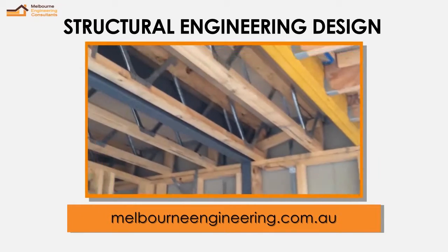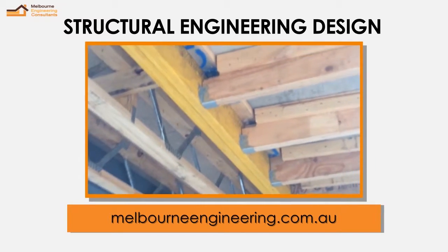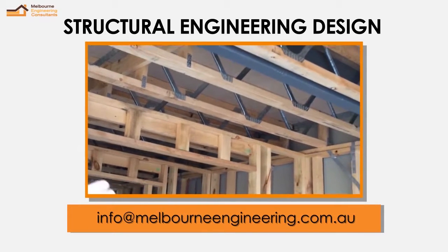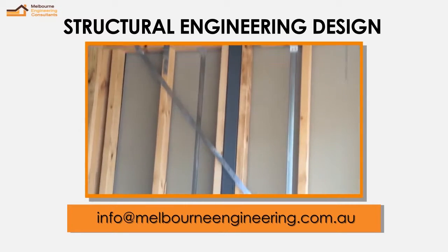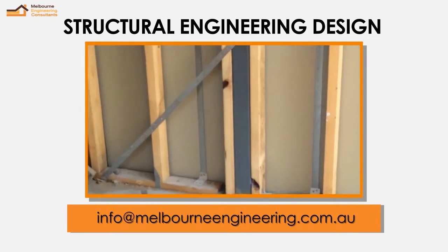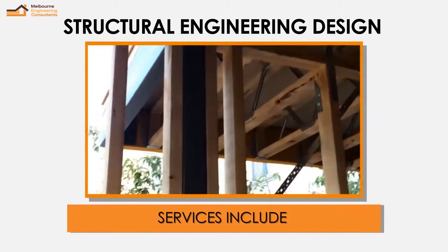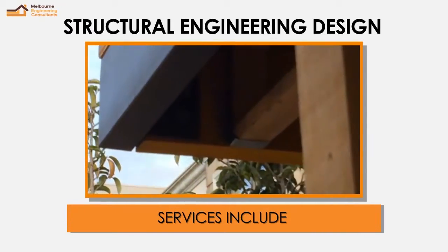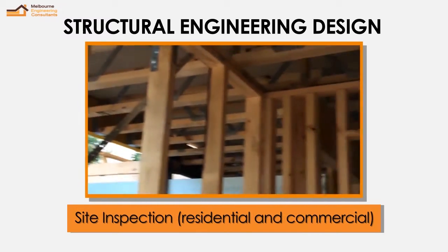So here we're showing the ground floor, so showing the balcony over. This is the balcony floor joists running out, and the internal floor joists at 450 centers which are posi joists, and I have my steel beam which is sitting on the post as a bolted connection, and the steel beam is coming out this way and cantilevering out and picking my other side's timber beam which is bolted to my steel beam. So all the posi joists in this direction are at 450 centers, which is picking my first floor level.